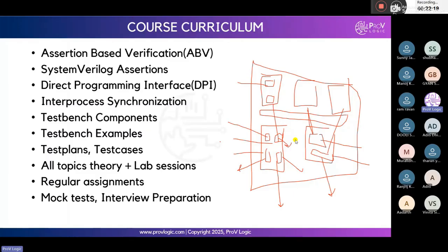Functional verification means, as we discussed so far through coverage, verifying the actual functionality. Formal verification means validating the behavior using assertion based verification. Mostly in formal verification we write assertions, coverage and assertions, because it validates the behavior. Every functionality is checked with respect to the design behavior.